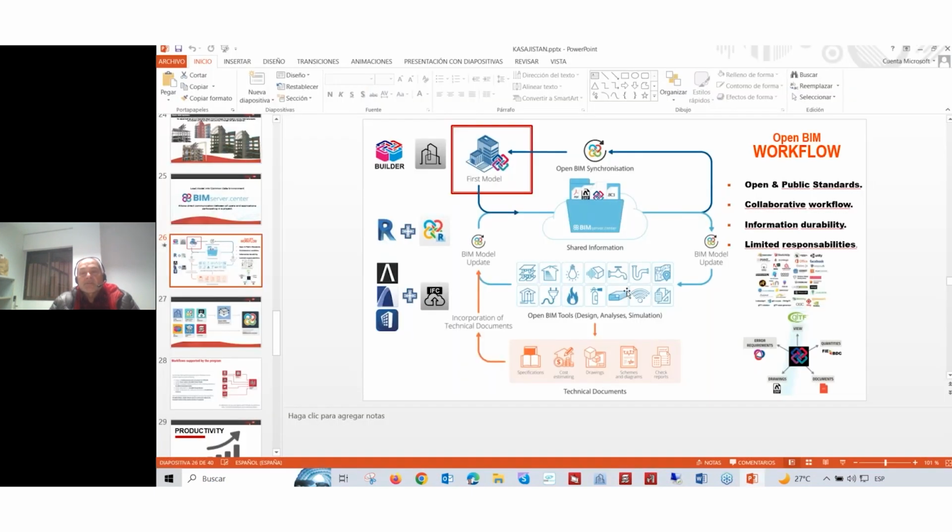In our BIMserver.center, we have the model. When you are going to work with Cype3D, you can export that information to Cype3D, and then you save time. You can copy, select the profiles, and start choosing whatever you need.